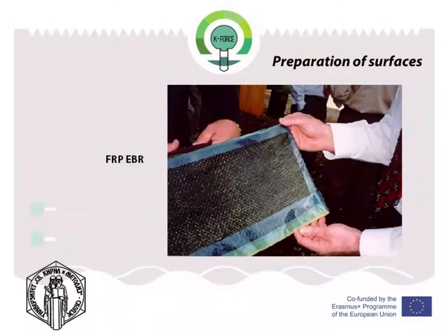For strips provided with an inbuilt peel ply, the ply should be removed immediately before application and the surface must not be touched by hand again. The strips should be handled with clean gloves and under dry conditions. They have to be verified for possible damage resulting from transportation, handling, and incorrect cutting.